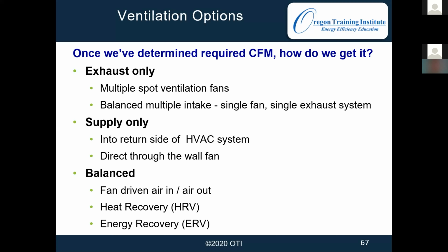Another technique that brings the air in is a fresh air intake on the return of the furnace. So that's another style that brings air in when the furnace is on. And then the third category is the balanced system.